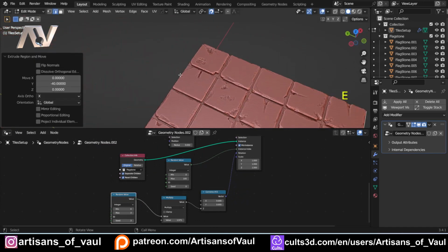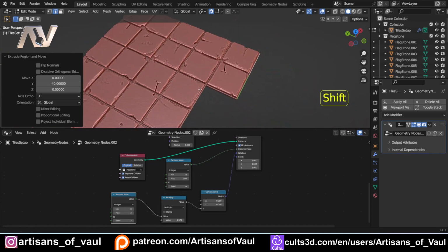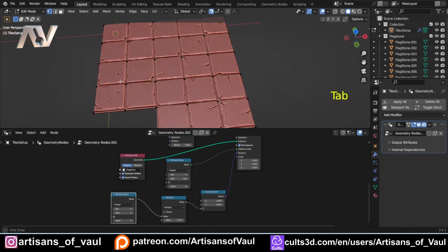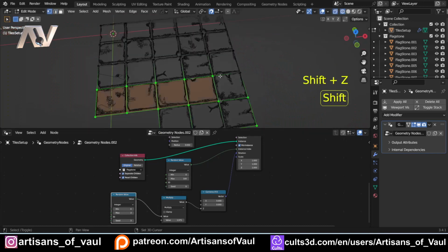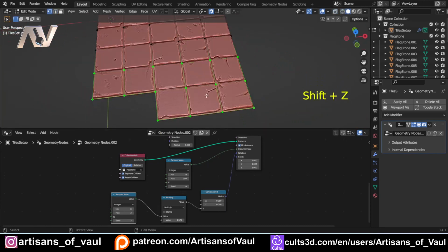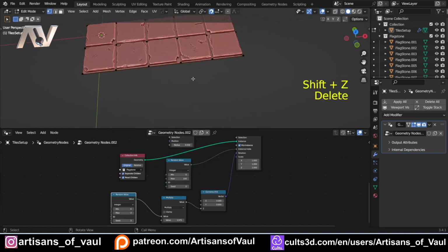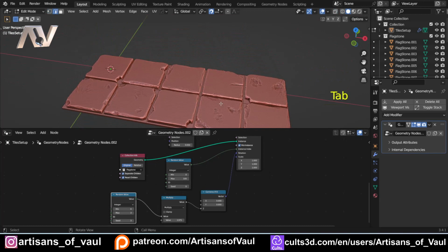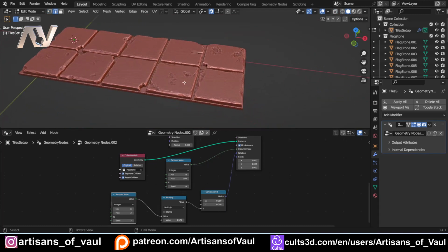As we saw, we can just press E to extrude that out if we want to do something like a junction. Just going to go into vertex mode and get rid of most of that, just because it's getting a bit difficult to show it on the screen. So let's do that and come back to here. So we've got this pretty much sorted, other than the fact that we do want to make sure that we can boolean this all together.